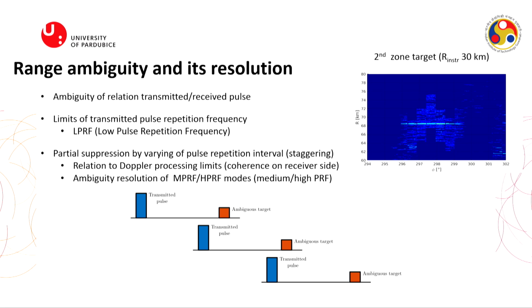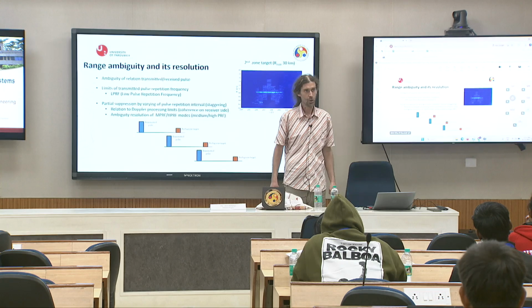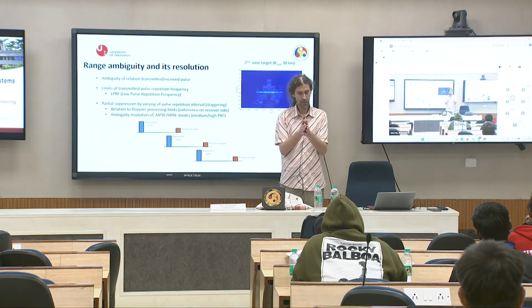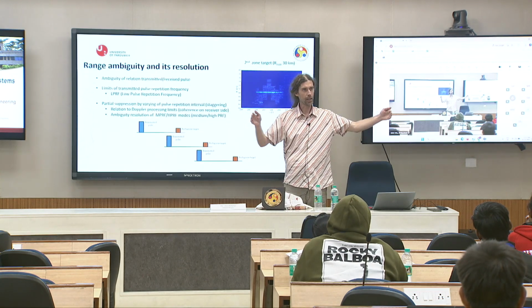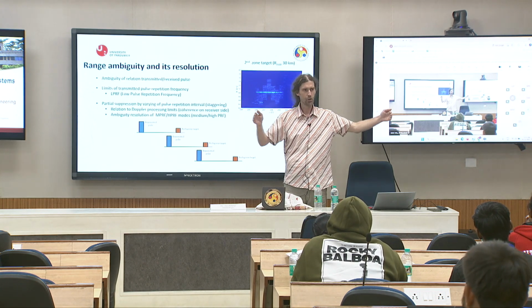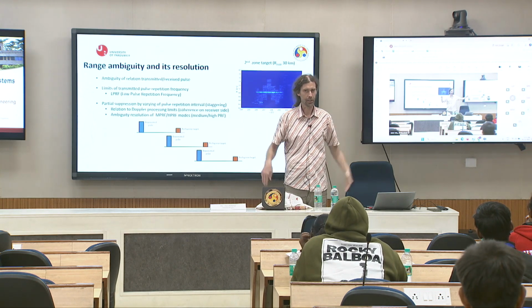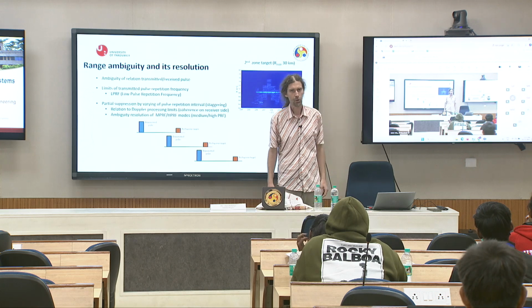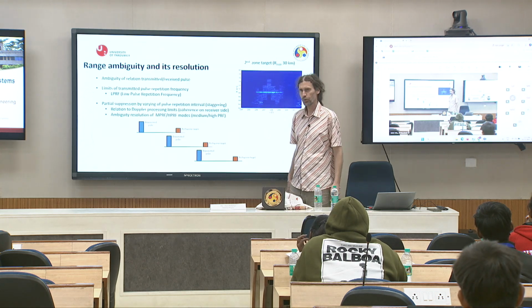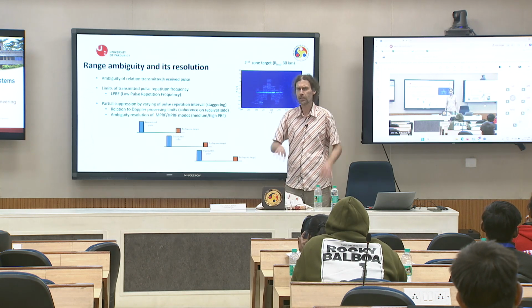And remember the short and long pulse that I showed you in a real radar. It is about these ambiguities. So we use different regimes because we can handle it. So okay, I can improve with a higher PRI, but Doppler will be destroyed, as you will see later, because Doppler is computed from individual pulses. I will show you.